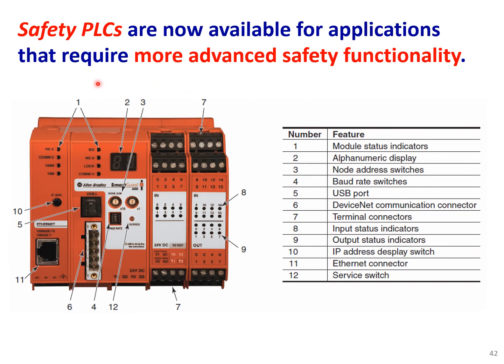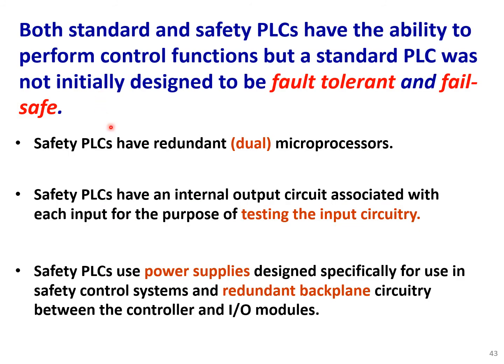Safety PLCs are now available for applications that require more advanced safety functionalities. Both standard and safety PLCs have the ability to perform control functions, but a standard PLC was not initially designed to be fault tolerant and fail safe.